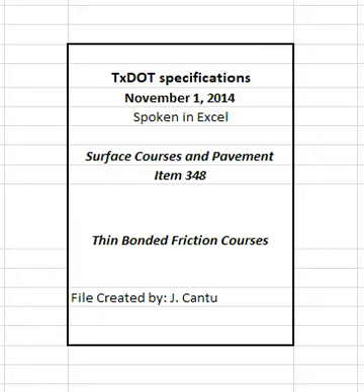2.7 Recycled materials. Use of RAP and RAS is permitted unless otherwise shown on the plans. Do not exceed the maximum allowable percentages of RAP and RAS shown in Table 5. The allowable percentages shown in Table 5 may be decreased or increased when shown on the plans. Determine asphalt binder content and gradation of the RAP and RAS stockpiles for mixture design purposes in accordance with Tex-236-F. The engineer may verify the asphalt binder content of the stockpiles at any time during production. Perform other tests on RAP and RAS when shown on the plans.